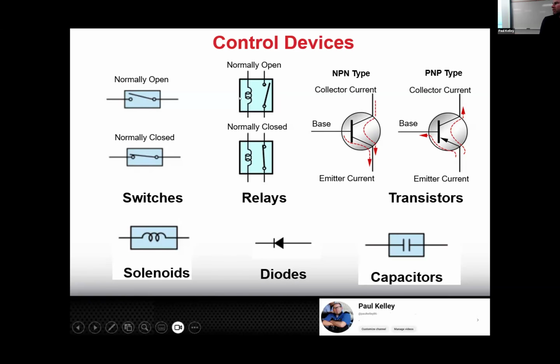We use a solenoid on the control side, and I call it the control side because it controls the relay, right? So the relay, if you think about it, everybody knows relays, oh, they click. Well, yeah, they click when you have 12 volts and ground on the control side, and that should magnetize and pull the switching contactor over, and that's the click a relay makes.